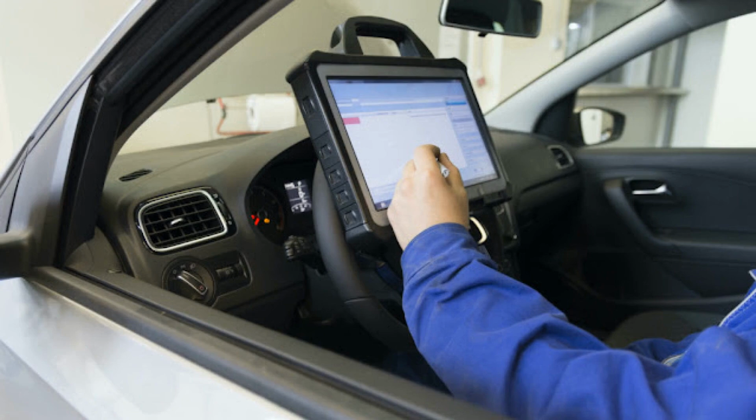Manifold Absolute Pressure (MAP), Mass Airflow (MAF), and Throttle Position (TPS) sensors monitor engine air intake in different ways. The MAP sensor measures air pressure in the intake manifold, while the similarly named but different MAF sensor calculates engine airflow volume, and the TPS sensor indicates throttle position in the throttle body.